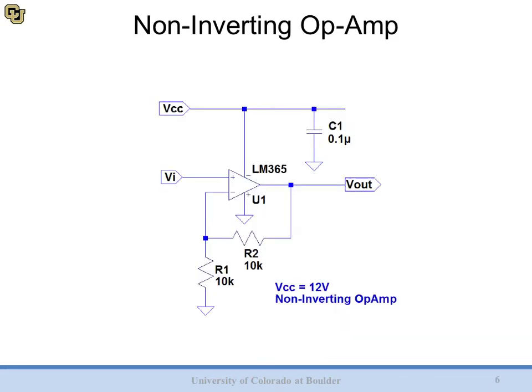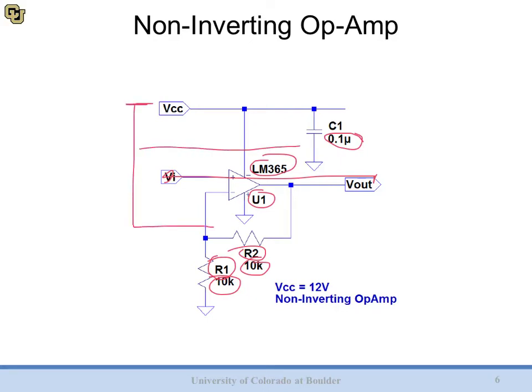Now all these same things we talked about will apply if we're representing our circuit in some sort of simulation program. This is a schematic taken from LTspice, and you can see again all of our components have designators as well as values. Data flow goes left to right. We've labeled things micro, not 10 to the minus 6. Even our op-amp has a part number and a name. Additionally, we have our voltage supply rails above our ground symbols. And because it's a simulation program, we were able to add a helpful text box to show us what this circuit should do. We like this. If you're implementing things in a simulation program, go for something that's clean and nicely laid out like this example.